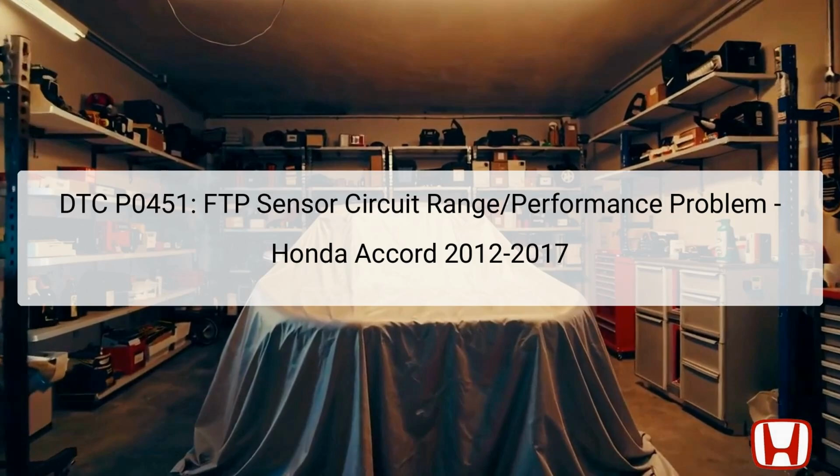DTC P0451 specifically indicates a problem within the FTP sensor circuit, which refers to the fuel tank pressure sensor. This sensor plays a crucial role in measuring the pressure inside the fuel tank, aiding in the monitoring of the evaporative emission system. An accurate reading is essential for the engine control module, ECM, to efficiently manage fuel vapor and